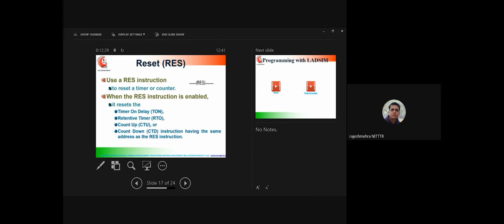Now, with the same address, I am using another down counter on the exit side, which has the same value. Once one car is exiting from the exit door, then your accumulator value will decrement by 1. Your accumulator value will become 99. Now, from the entry gate, one more car can be allowed to enter the parking. So this is basically your automatic parking system.